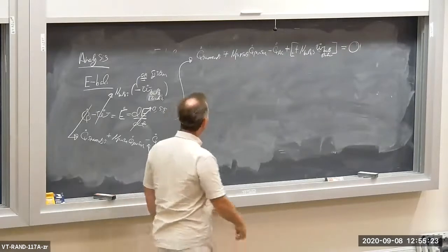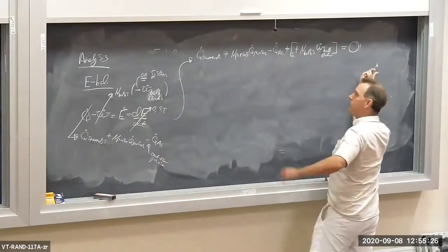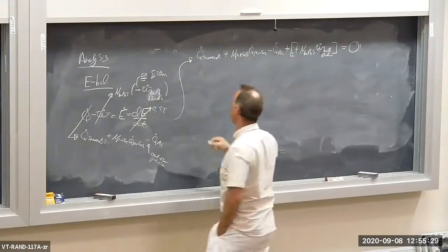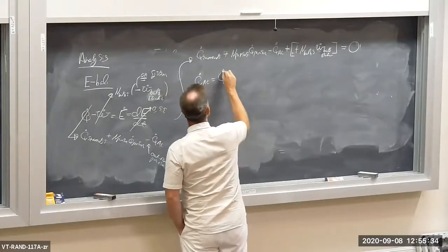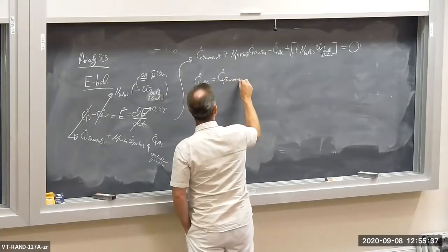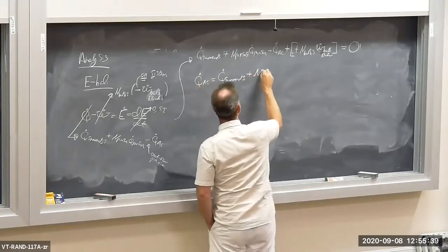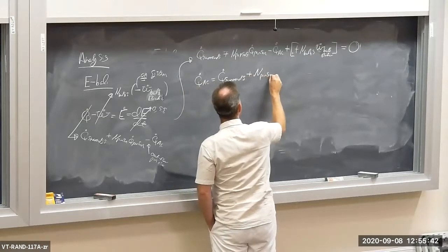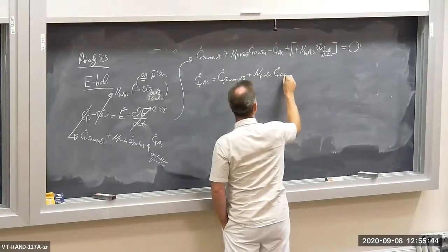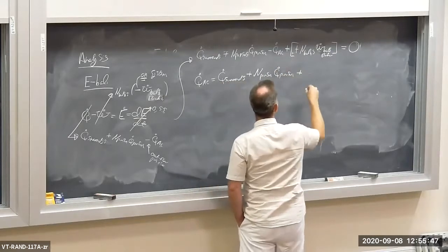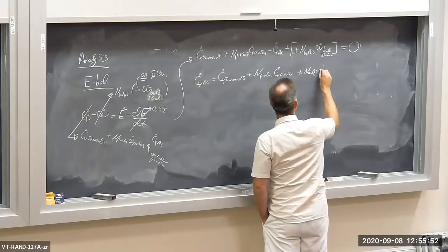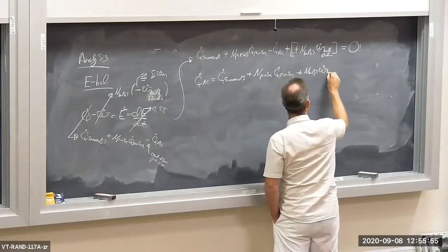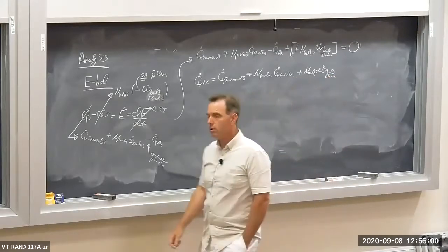So let me move Q dot AC over on the other side of the equation and flip the whole equation. Q dot AC equals Q dot surroundings plus n persons Q dot person plus n bulbs W dot bulb electric. Okay?